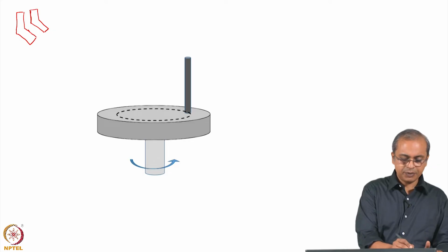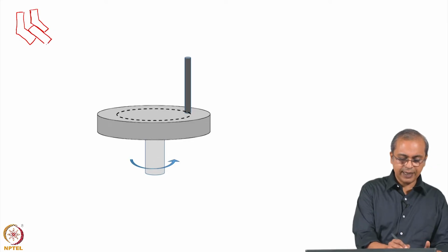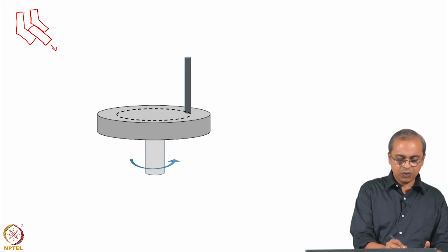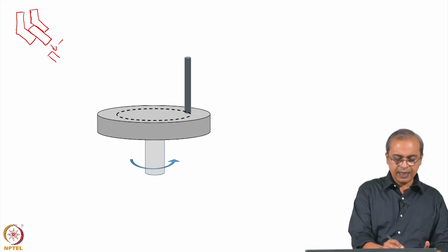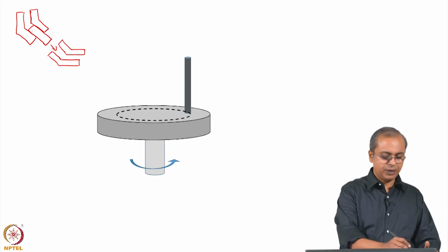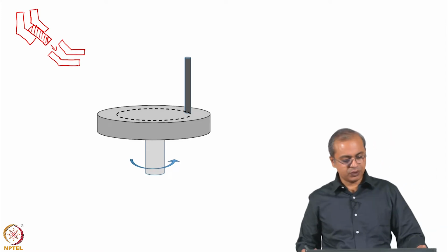And so, the sample that comes out still has this cross section that it originally had, but it has already undergone significant severe plastic deformation, and then you can put it through one more pass like that. So, this is just an example of what you could do. The angles that are there can be changed and various things you can do with it, and that is your sample that you repeatedly send through this process.